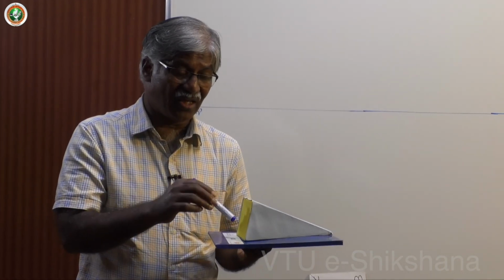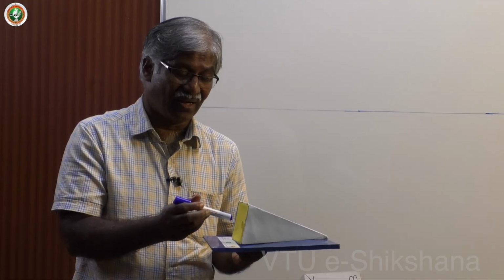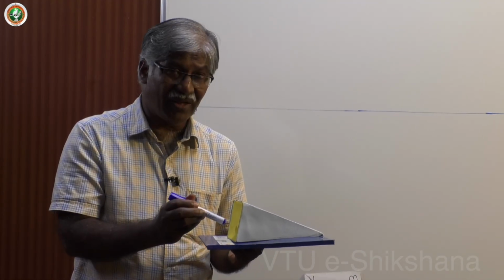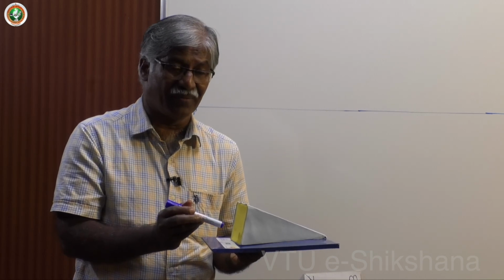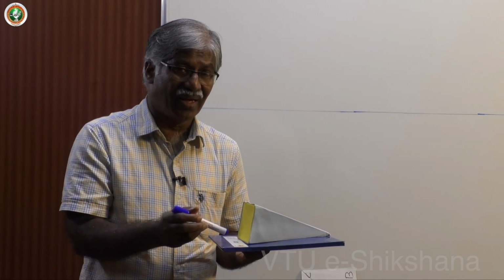Once the slant face is on HP, definitely the axis is inclined, but by a very small angle, around 30 or less than 30, depending on the size. Anyway, it is inclined; correspondingly get the apparent length. That apparent length must be placed on the apparent inclination. In this problem, the axis is given directly, so we have to find beta and then redraw the figure.